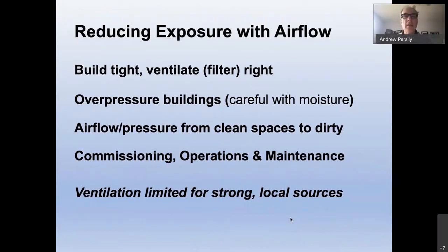People have been saying that since the 1980s, and I added filter to the ventilation concept. You can overpressure buildings to keep the outdoor aerosols from infiltrating, and that's a good concept, but you have to be very careful with moisture management when you do that. The third concept is to manage your airflows and your pressures so that the air within the building flows from clean spaces to dirty spaces.